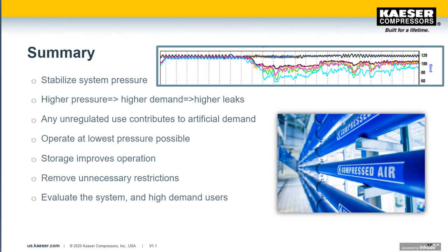If you look, you see a lot of different pressures down there with different colors. I like a lot of color, so there you go. But you see some of those pressures drop down to about 60 pounds. These pressures were all put out in different areas of the facility, and so this is what users are actually seeing as the demands hit. But the interesting thing is the compressor room doesn't see any of that.